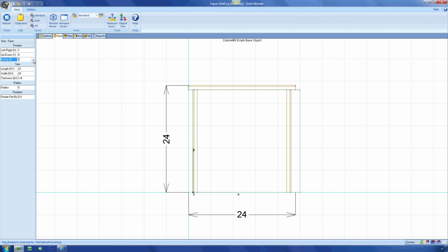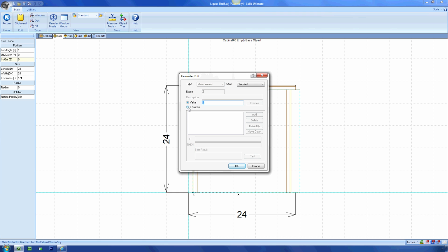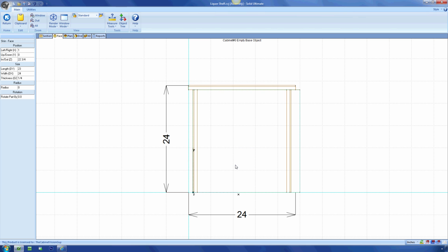The Z location will be the depth of the cabinet, minus the face inset value, minus the thickness of the skin's material, which makes the equation cab.dz minus cab._face inset minus _m:/dz. Now, we haven't worked with the Z location yet, but this is the first of several times that we will. What we are setting here is the part's origin point's distance from the back of the object.